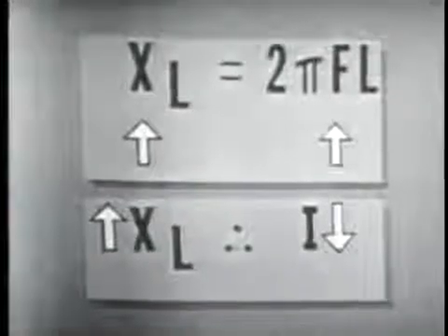Now, we know if the reactance of the rotor increases, then of course the current in the rotor is going to have to decrease. Right. So at this high frequency of cutting, that is when I'm holding it stopped, the reactance of the rotor becomes large enough to limit the amount of current flowing in the rotor's conductors. So too great a load will stop the rotor by increasing its reactance to a point where the current decreases. And of course, as the current decreases, the strength of the electromagnetic field decreases, the motor can no longer do its job, and it stops.